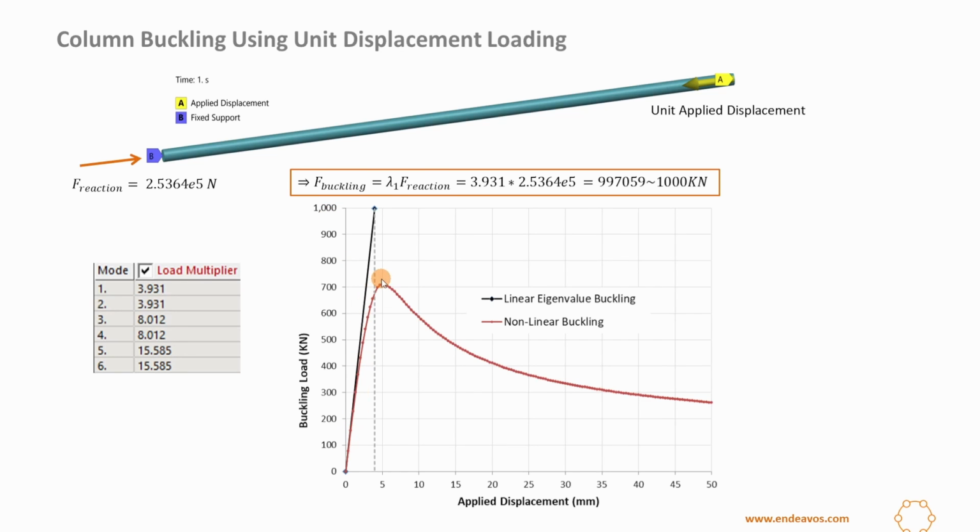And this is the chart that I'm getting for the nonlinear case. So once again, I'm getting very close to 700 plus kilonewtons, just slightly above 700 kilonewtons, which is the same result as before. Now the question is, where do we set our design or allowable load for this rod problem? Allowable load meaning when you're designing it, the design load cannot exceed that load. It's not 700 kilonewtons. It has to be some value below that.